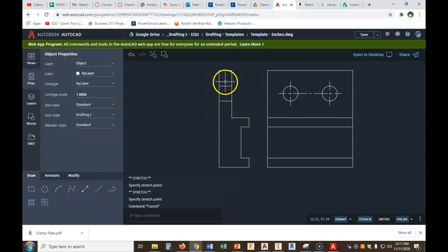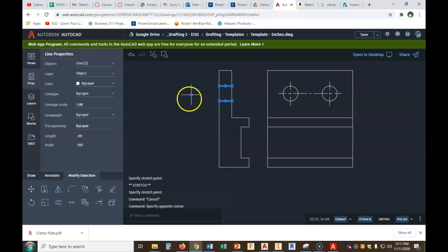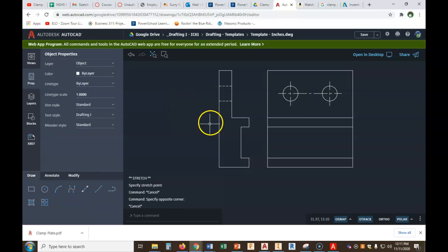Now both of these are hidden lines. So I'm going to click and drag across. I'm holding down my left mouse button. There, I got them both. Change their layer. Look, it even tells me to. Drop down, say Hidden. And there we go.